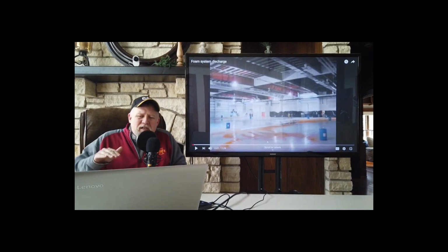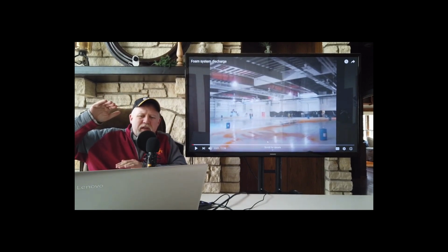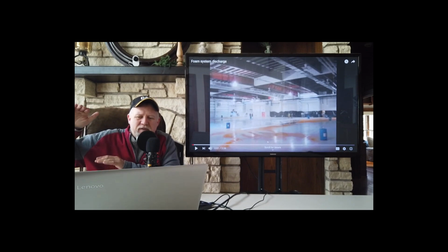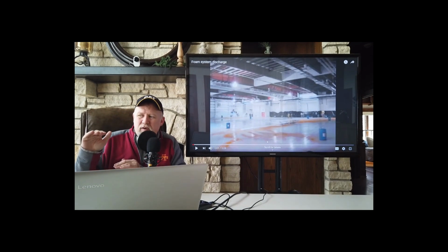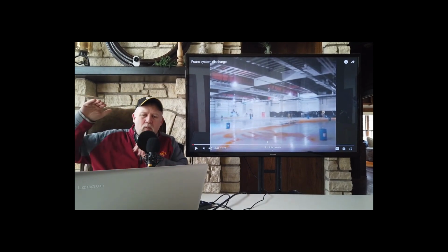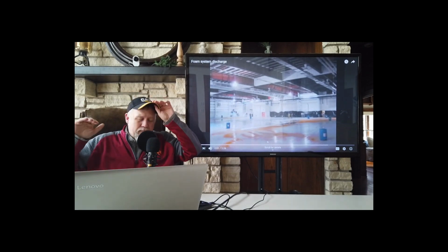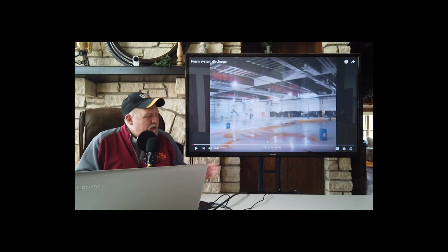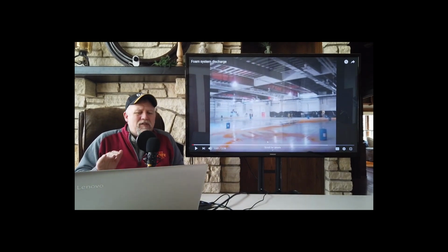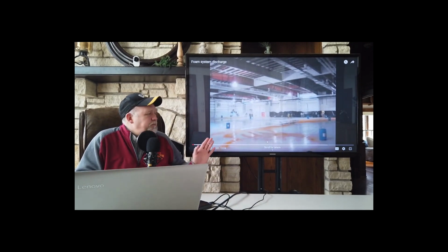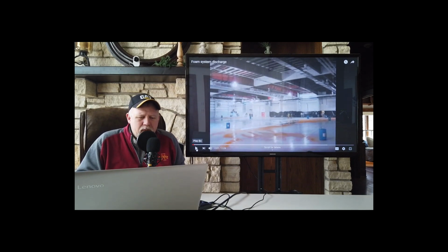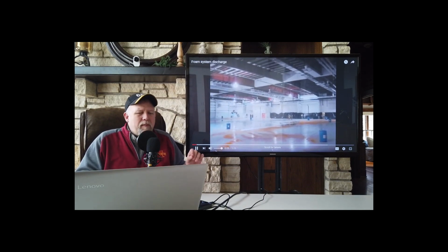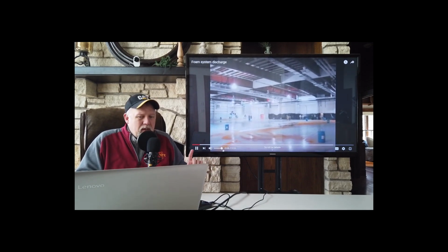In other words, you design it to go up to the height of the fuel tank specifically for a Black Hawk helicopter, if this is where Black Hawk maintenance is done. If you're doing it for, say, a 747 or a jetliner, you're going to design it to go up to the wings, because in most of the jet aircraft, the fuel is held in the wings. So you have to put in as much foam as it takes to cover it. Now, it's not going to drown anyone. I want you to think of the foam as almost like soap suds. All right? So the way this works, either with a manual or an automatic detection, right?